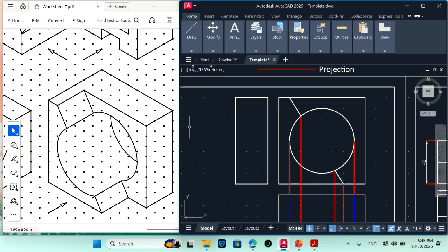So again, to locate the boundaries of the curved surface, these 2 points I need to check on the side view. First I will draw this curved surface lines. This is the 30 mm. So this is the 30 mm, 1 2 3. So I need to on the snap, F8 F9, and then I need to identify these 2 points.